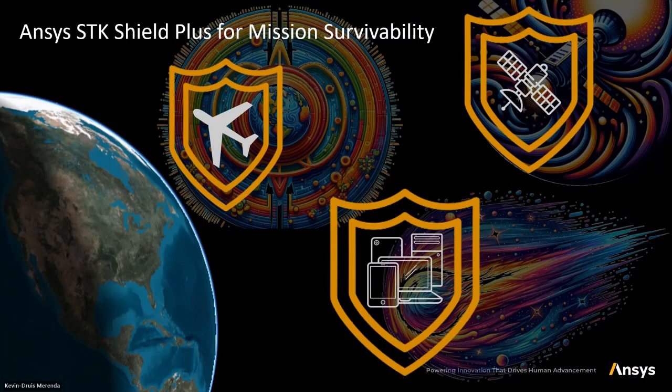What model formats can be used or imported in this package? We typically use the Discovery format. So you can open the Discovery interface and set up the problem in the CAD geometry. And then we will use that. The Discovery interface can load any STEP file, any CATIA file and object files that you may have from your other CAD tools. And then STK Shield Plus will load in that Disco file.